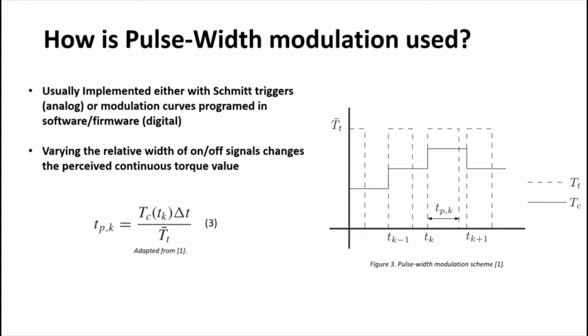For lower required torques, it is clearly seen that the thruster is firing for a smaller percentage of the cycle, while higher torques result in longer thrust durations. It is important to note that in this example, the discretization and PWM cycle duration is the same. Depending on the system's characteristics and constraints on the thruster's firing times, it could be possible to have multiple pulses, or PWM cycles, in a single discretization period.